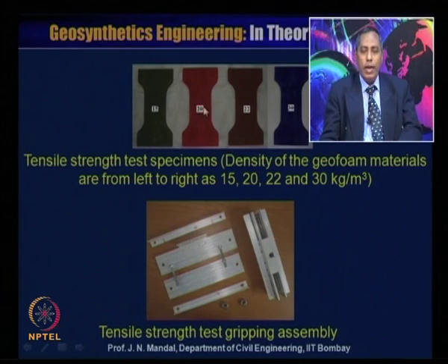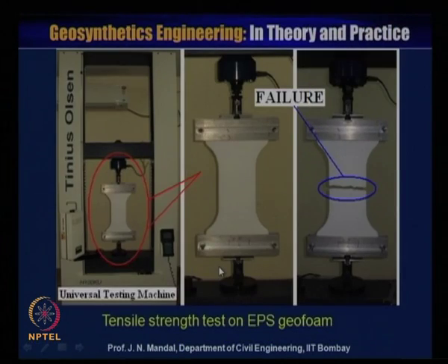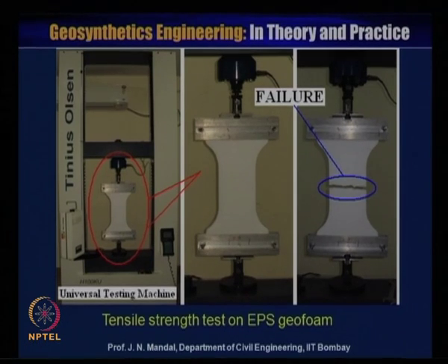So, this is the testing sample with different densities and this is the gripping assembly. Here we are performing the tensile test on the expanded polystyrene geofoam.